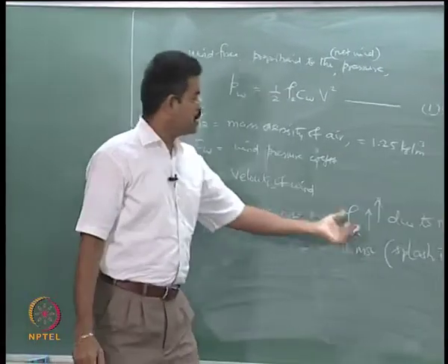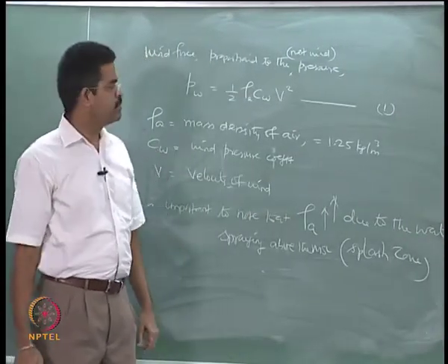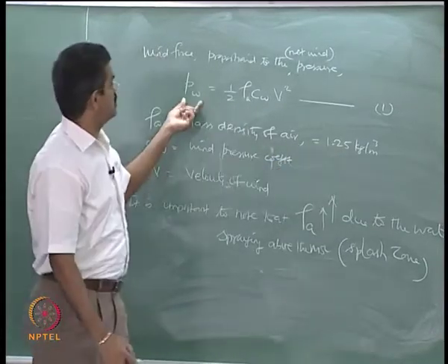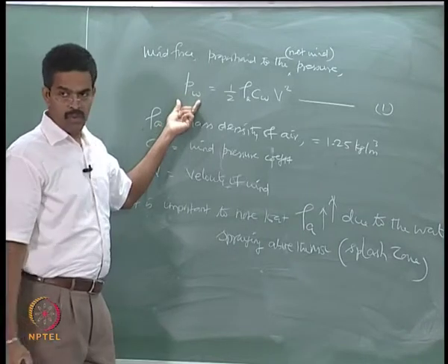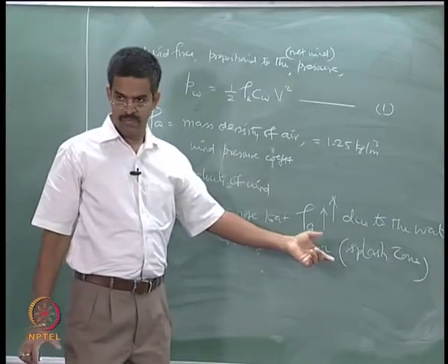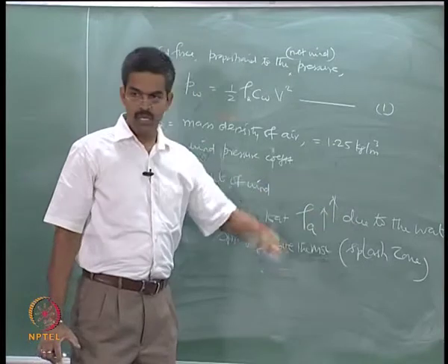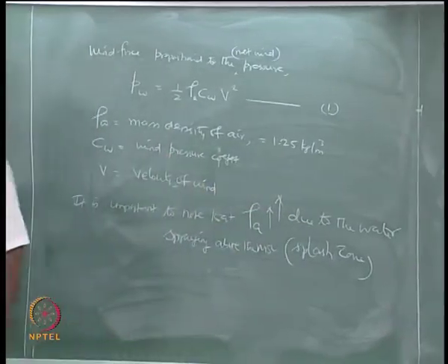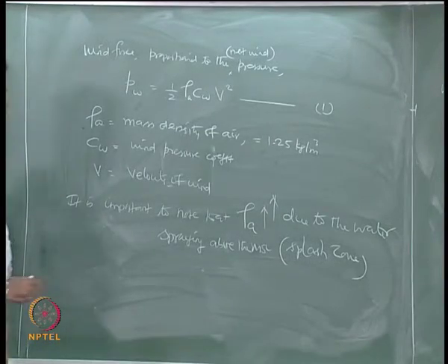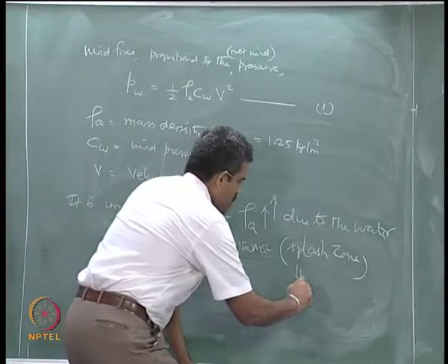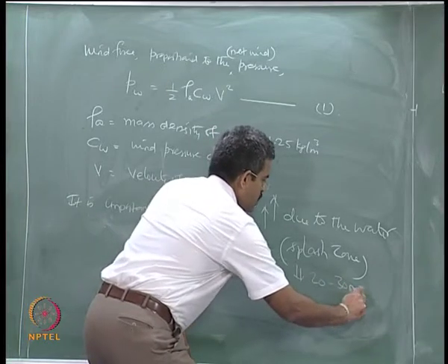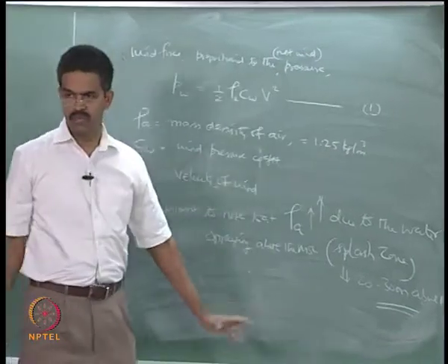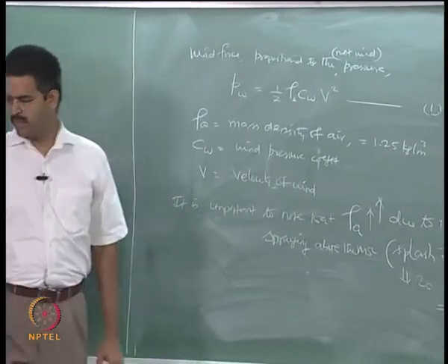So, this keeps on increasing. So, the estimate you make with this number as the pressure acting on the member is not accurate whenever you are talking about members in the submersion zone or in the splash zone, and that splash can happen to a value of 20 to 30 meters above MSL. You see, it is as high as this value.